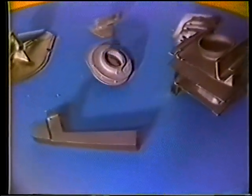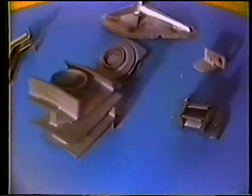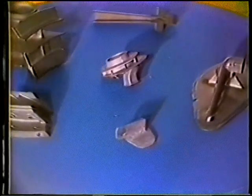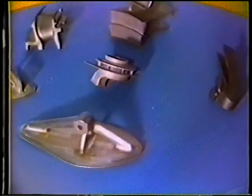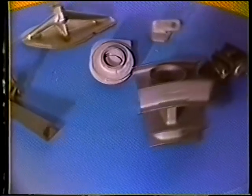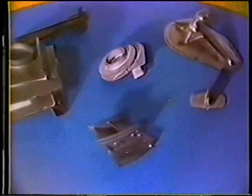Many of the metals used in making aircraft engine parts have melting points greater or equal to the melting point of the metals used in making the molds for permanent mold or die casting. In these cases, thermal shock can cause cracking of the mold. Investment casting presents no such problems. This unique combination of qualities makes investment casting ideal for the manufacturing of high-stress aircraft engine components.